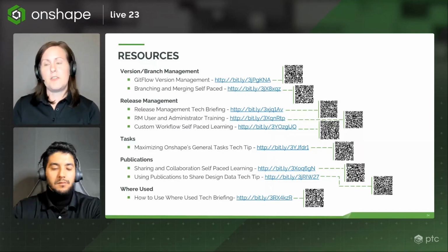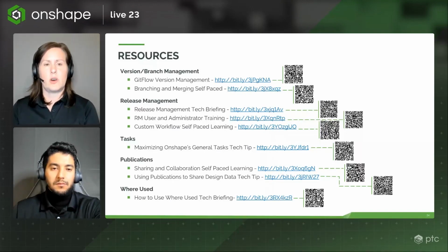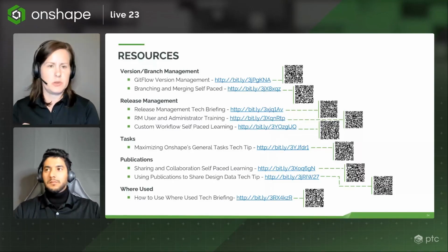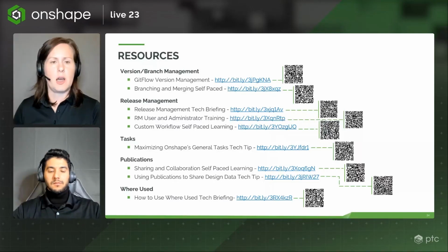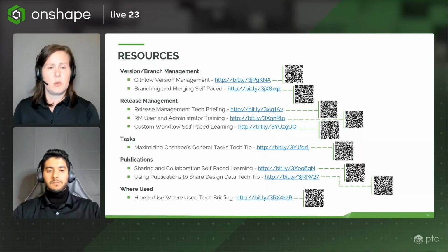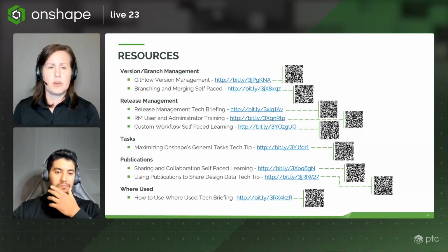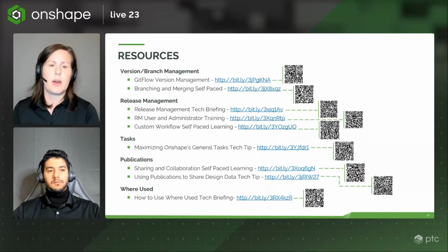Okay, so first off, every change you make in the document is stored in what's called a change. Those were the little blue dots. You can also create defined versions, which are the large blue dots. You just select the button in the very top, and that will create one. Those are good for milestones. There is no limit to the number of versions you can create, but the more versions you create, it may be more difficult to find what you're looking for. So it's good to do it intentionally. And because every action is recorded in the version history graph, you can go back all the way to the point of creation. So every single action can be undone or redone.